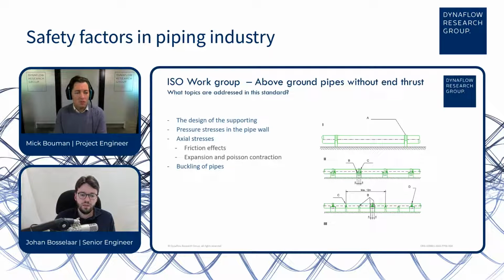Is it a high pressure or low pressure application? Typically, the pressures are not that high for these systems. There will be 4, 6, perhaps 10 bar. You could make them a little bit higher still, but it's not 100 bar pressure piping. It's typically large bore, because it's a transport of a lot of water.